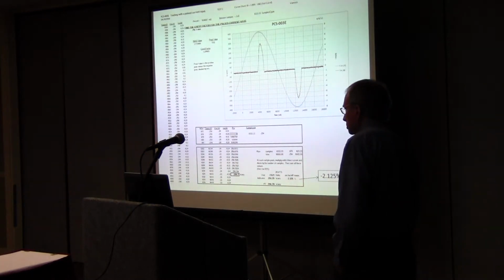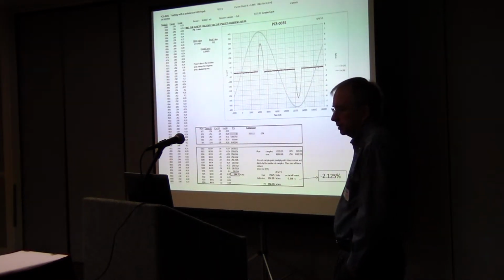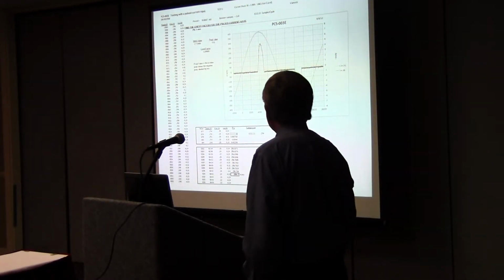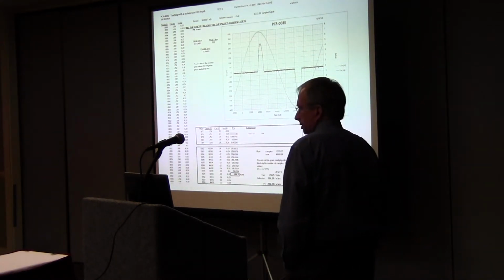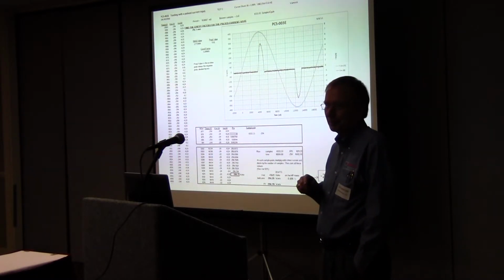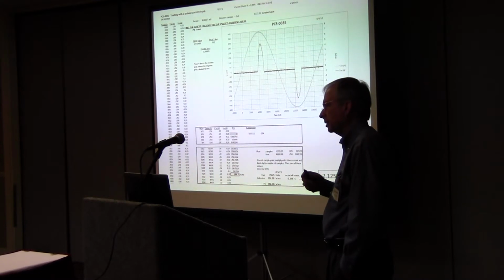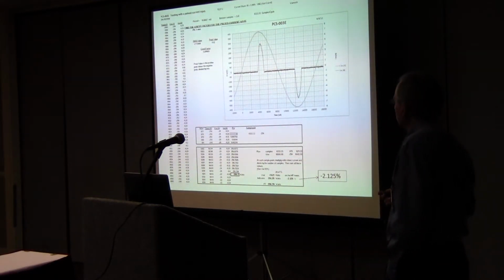So what we did was we took our transducers. This is a particular model of one of our transducers, and it's the Hall generator type. And we used one of Hewlett-Packard's programmable signal sources. We took that waveform that I just showed you, and we programmed it into the signal source so that we could create a current that was exactly like the current that they were trying to measure, and we put it into our PC5.